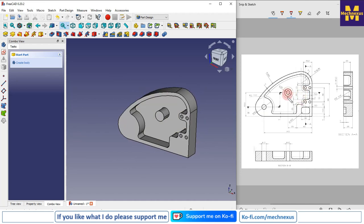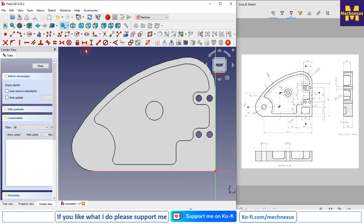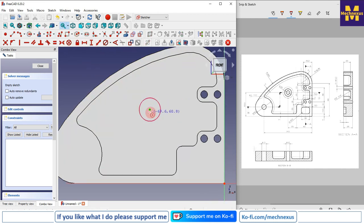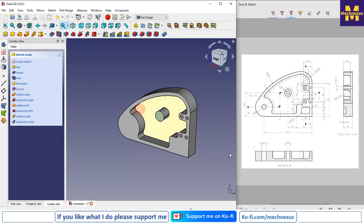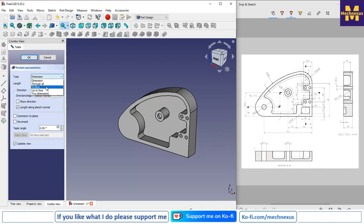Now there is a hole on this boss, so I will select the face and create a sketch, and I will convert the outer geometry. Now select the circle, and this hole dimension, cut hole dimension, you can find here, which is of diameter 10. So I will select it and give it a diameter 10. Now I will close it, and this hole is also a through hole, so I will select the cut and simply say through hole.